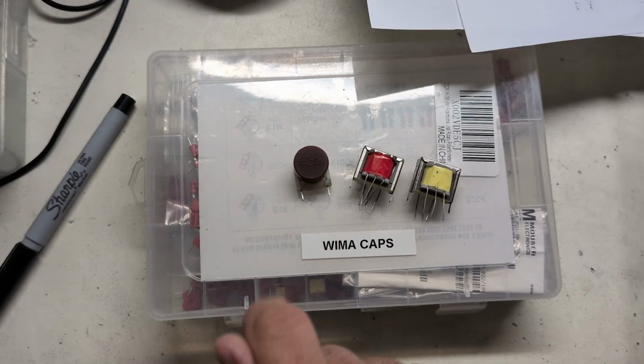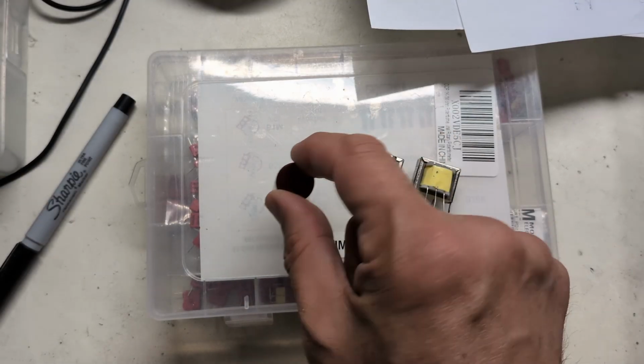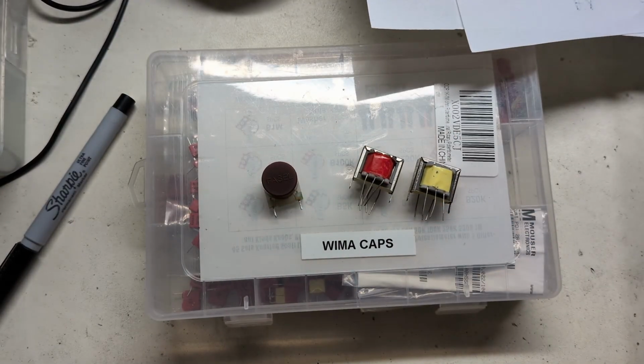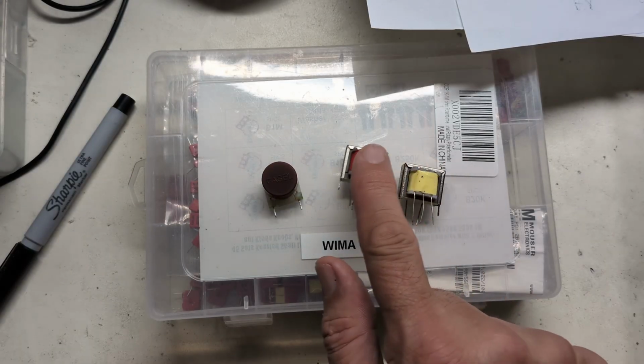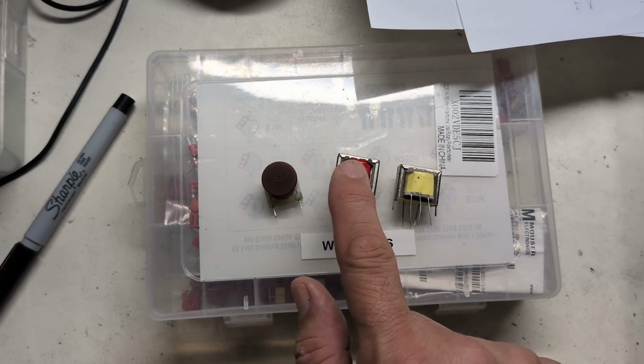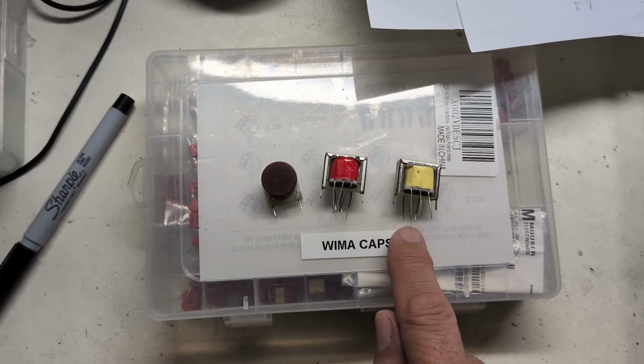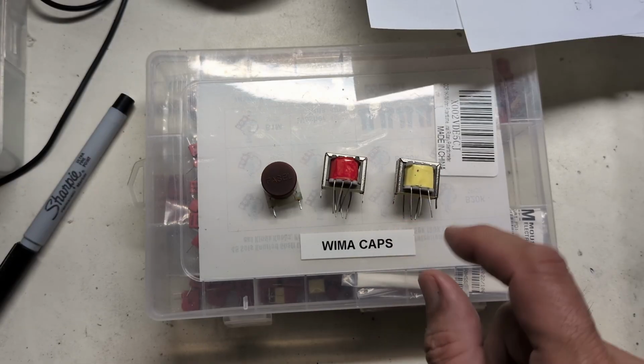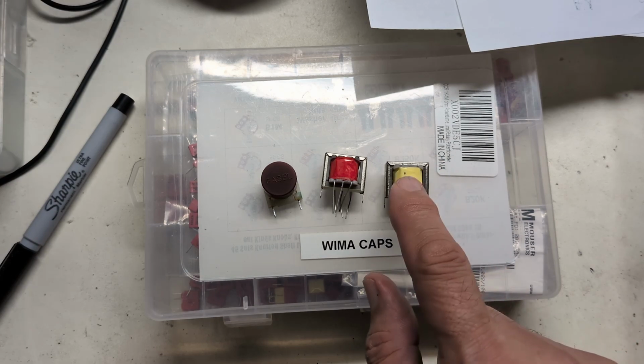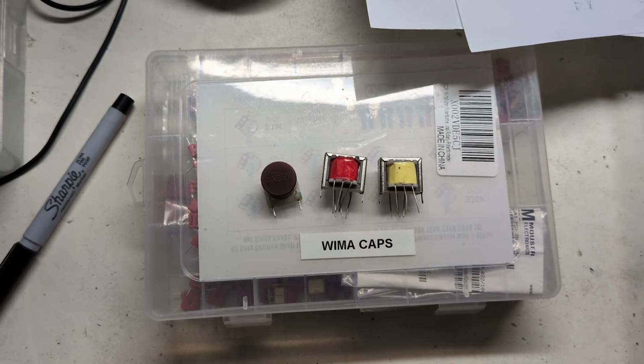This is one from a wah-wah pedal. This is in the millihenries, and so we're looking for something more like 8 henries. These two might be better candidates. This is 600 ohms impedance, and this is 10k impedance. So this one looks like something that might be a better approximation to a guitar pickup. So I'm gonna use this, and we're gonna look at how we would now place that with a buffer.